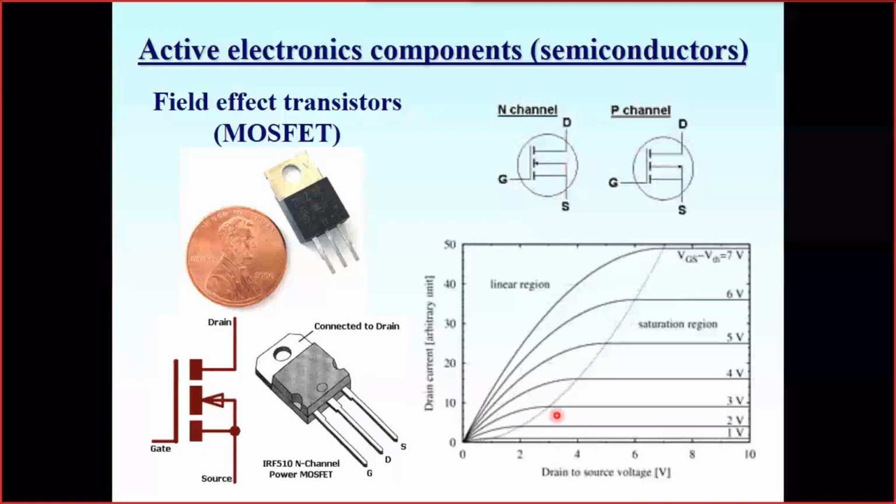So the volt-ampere curve is quite similar to that of the bipolar transistor, and we see here the same drain to source voltage. There is saturation of the current at a certain drain to source voltage, and we see that these volt-ampere parameters alter depending on what voltage is applied to the gate. So the higher the voltage, the more current the transistor passes.